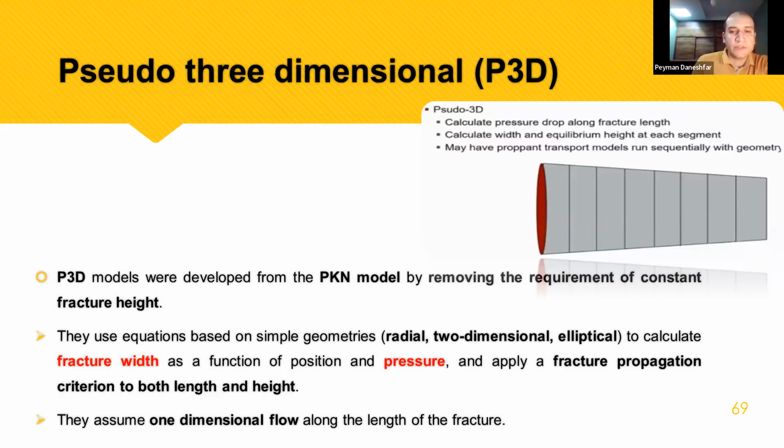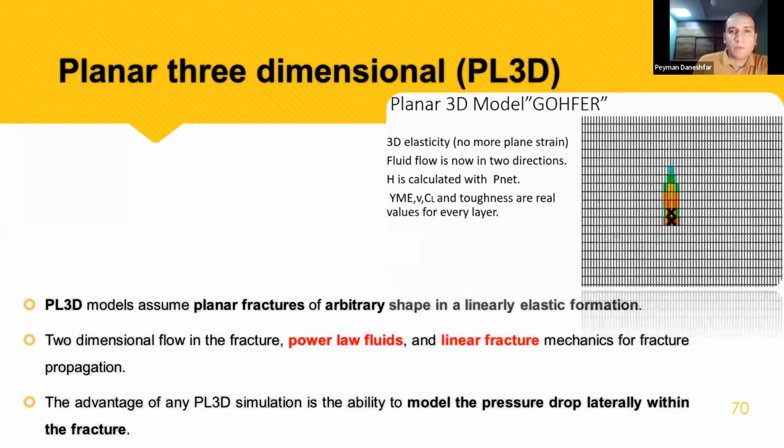And another one, planar 3-dimensional or PL3D, is used in one of the famous software packages on the market, GOHFER. PL3D depends on planar two-dimensional flow in the fracture, power-law fluid flow, and linear fracture mechanics for fracture propagation. And the advantage of the PL3D simulation is the ability to model the pressure drop laterally within the fracture.